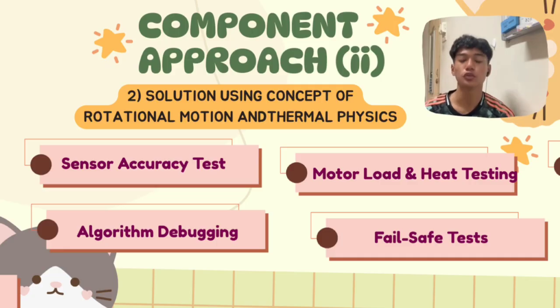Next, we do the motor load and heating testing. This involves running the motor at different speeds and monitoring the actual temperature changes. We compare this to the expected values to ensure that the motor isn't overheating during high load.